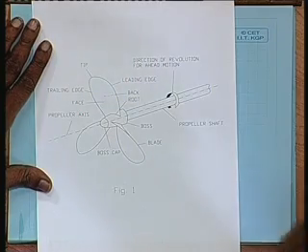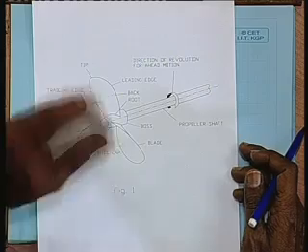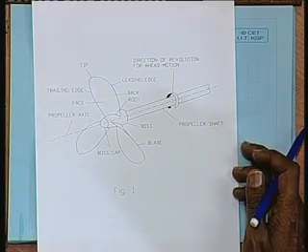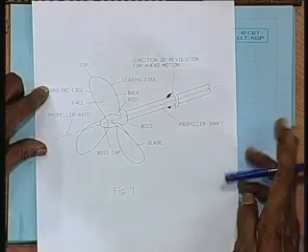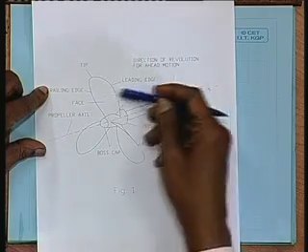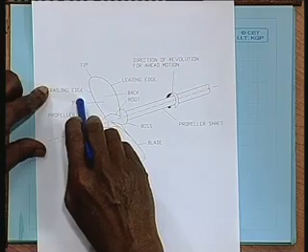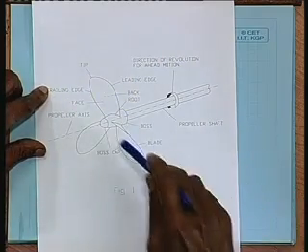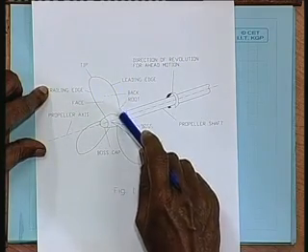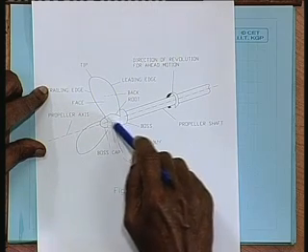Clearly visible? Right. So, this is the shaft where this shaft is rotating in the clockwise direction looking from this side, and this is the face, this is the back, leading edge, trailing edge. This is the boss, this is the tip, and this is the root where the propeller joins the boss.